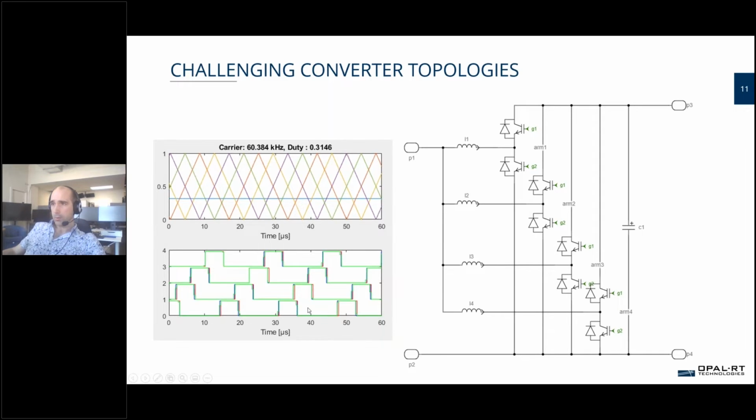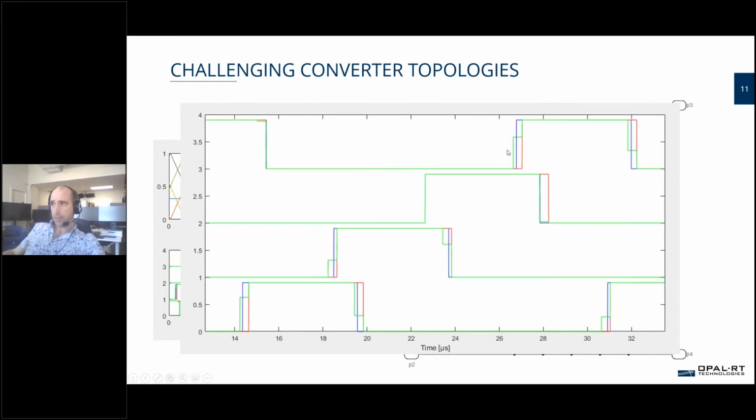So let's have a closer look at the interpolation. Like I already explained, the idea is that whenever there's a transition that occurs exactly and is synchronized with the expected PWM, then we won't have any interpolation. It's going to be the right signal, like in the case here. But if the transition occurs towards the end, then we're going to have a smaller fraction. If it occurs at the beginning of that step, then there's going to be a different transition. And using those values in our simulator, we're able to have a very high accuracy on this simulation.